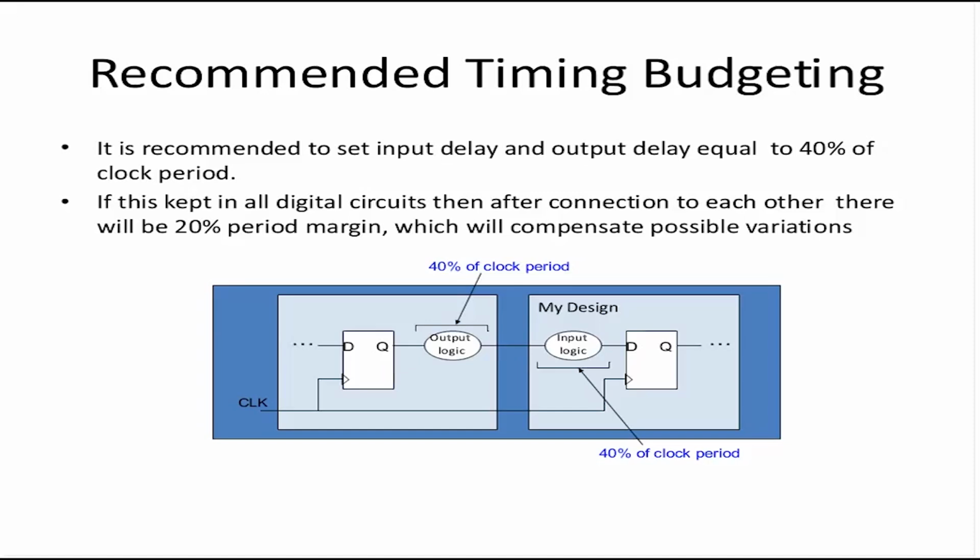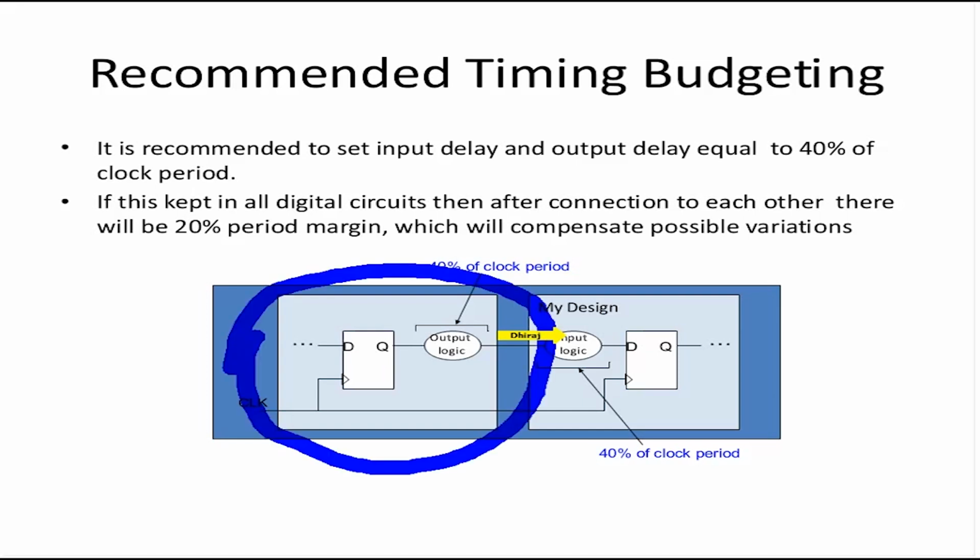Now there are a couple of recommendations for RTL design, which is to include registers on the inputs and registers on the outputs. Why is that? We do not know what kind of logic is going to drive the input port of the design. For example, this is my design, and I do not know how heavy this external world logic is. If we do not know how heavy this is, and if we consume more delay between this port and the clock here, then it is going to be detrimental when connecting to the external heavy design.